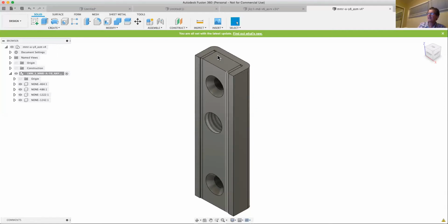What I have seen happen in the distant past is giving a very complicated component to somebody who's making the tool, and they have trouble importing it into their CAM package. But I've not run into CAD problems with step files. Step file is very robust. There is no history that comes along with it.